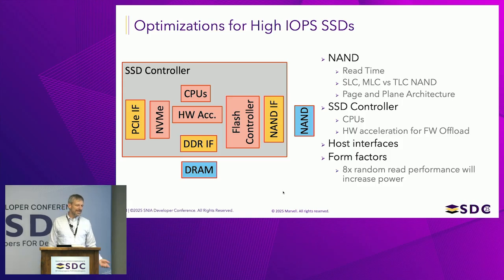So what is needed to really develop a high IOPS SSD? I'm showing here the block diagram of an SSD controller. On the host side, you have a PCIe interface. On top of that, you run the NVMe protocol to talk to the host.